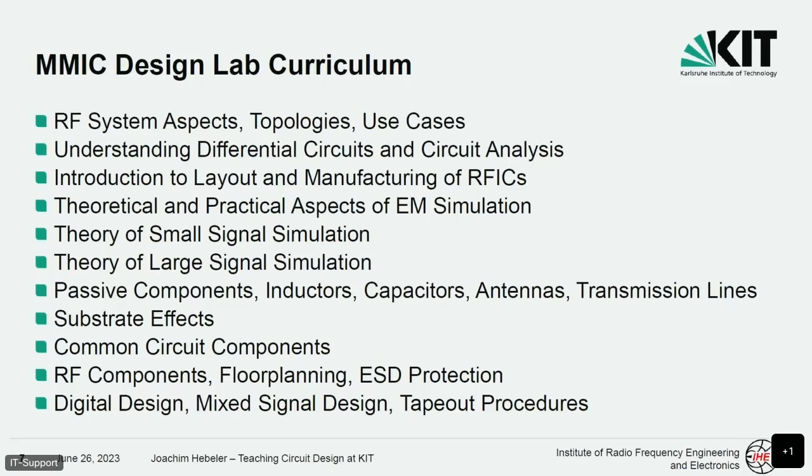We also want to talk about all these secondary things. What's the substrate effect? Why do we care about this? Why is there something happening? What are thermal effects? Why do we care about this? What are common centroid designs? Why do people fill their wafer up with dummy transistors? Why does this all happen? It's stuff that's not really necessary for RF design. You can just build your amplifier and be done with it and just click the filler generation script and a working circuit pops out, hopefully.